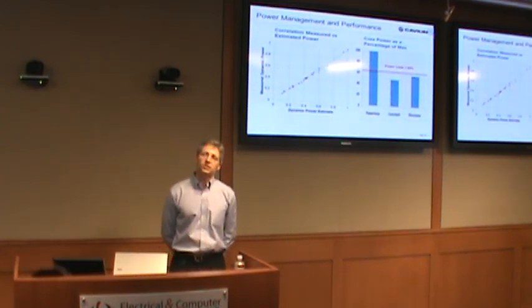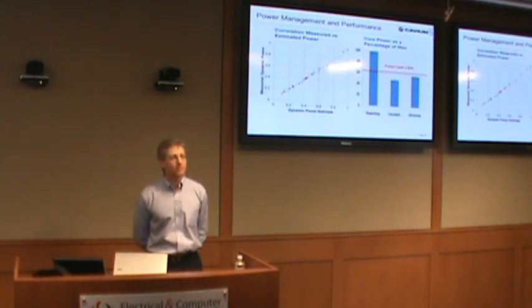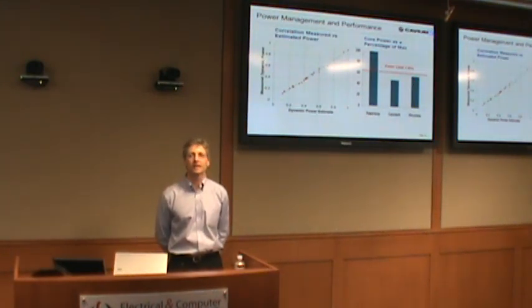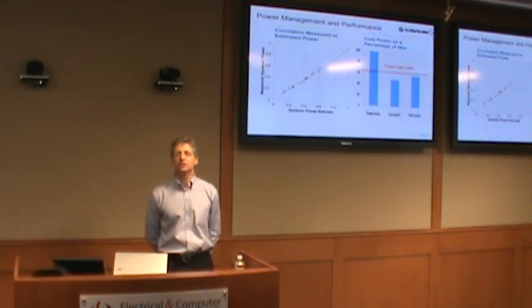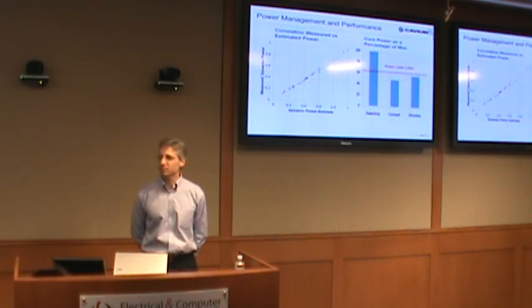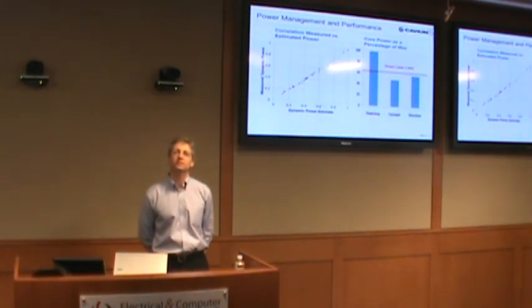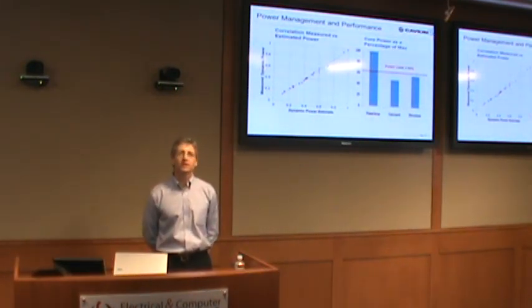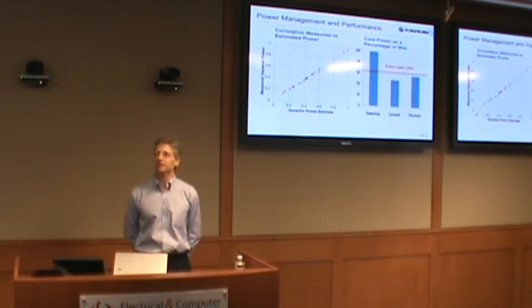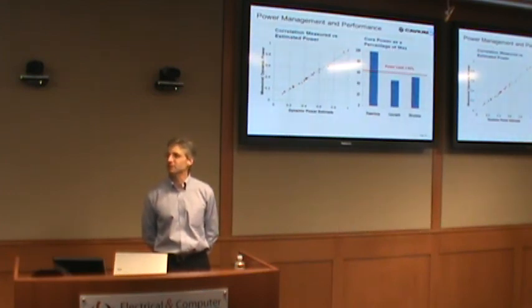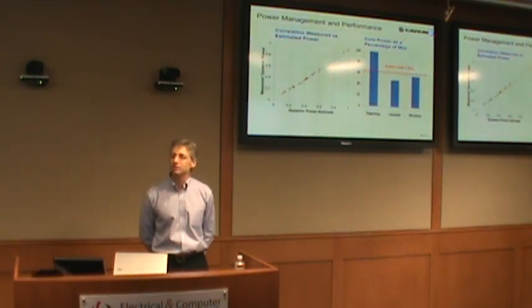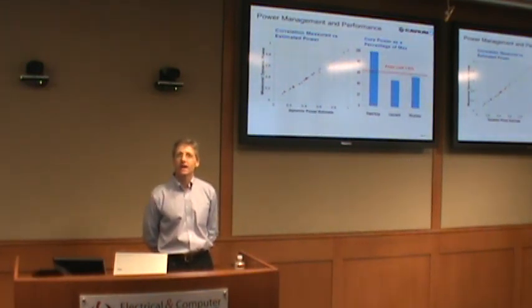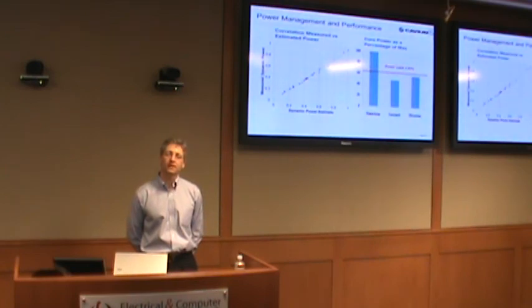So what we can do by putting in, say, a hardware limit of 65% or whatever the right number is you like in this diagram, instead of having to build your system, your chip, and everything for a value of 100, you can build your chip and system for a value of 65, and that's a big difference in the amount of power you need to be able to supply on the board and heat you need to be able to remove from the system.